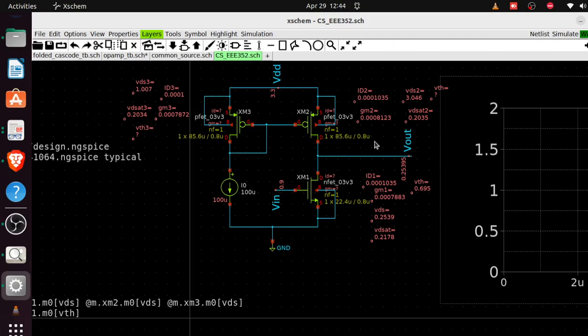You can see the operating point is telling us we are good. For your design to work well, everything needs to work well. You need to do the operating point analysis, verify, go ahead and check the transient, and check the AC. Actually everything plays together. Operating points can affect the values you get for your transient and for your AC analysis.